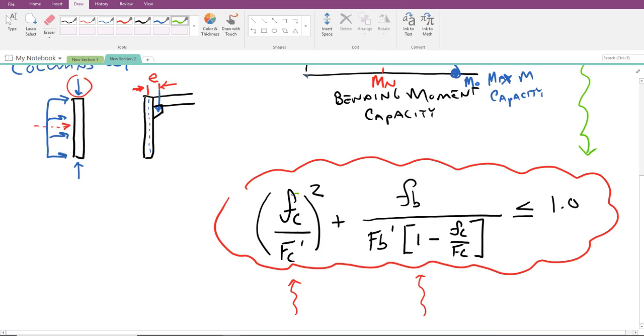So long as you calculate the compressive stress actual, compressive stress allowable, bending stress actual, bending stress allowable, and then note over here, this is simply the actual compressive stress that we're dealing with, and so there's no new terms in there. What I like to do is calculate these 4 values separately, just plug them into the equation, and go ahead and solve the interaction equation. Make sure that we have sufficient capacity in the column that accounts for compression and bending.